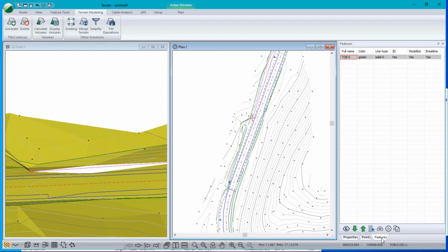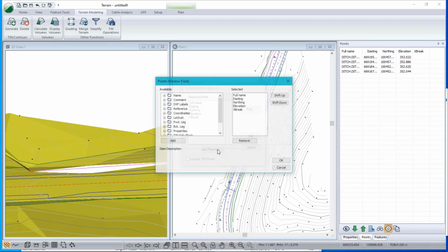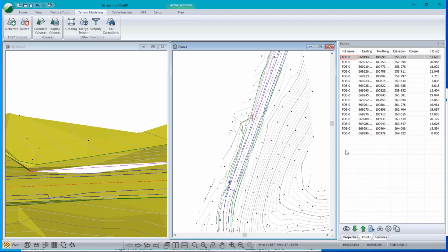In the features panel, you can display, nope, we're in the wrong panel, sorry. It was the points panel again. In the points panel, you can display, right, the options are this guy here. You can display the length of each segment, forward leg, HD, that's the length of each segment. And we're looking at that break line right now. There it is. And if I sort by length, oh, I said it was 79, but it's actually 57 is my long segment. But if you saw something in here that was like 507, well, you know that's probably not reasonable.